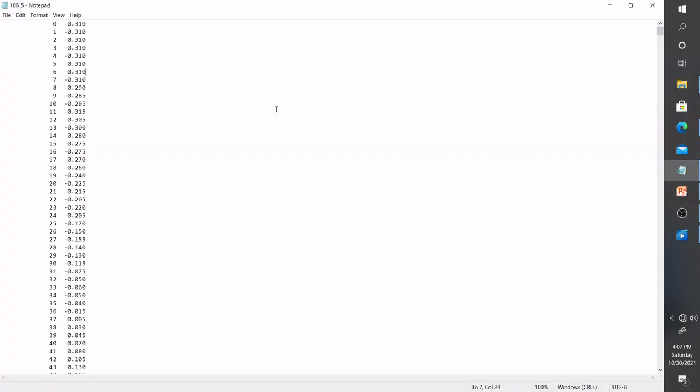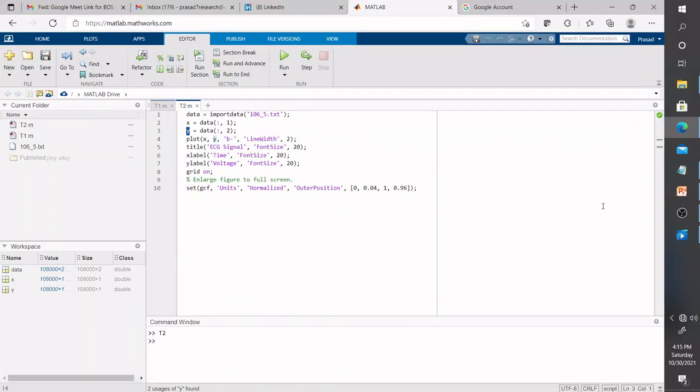According to the sampling frequency of 350 Hz, these are the samples we acquire at the output end of the sampling block. It has two columns. The first column is the number of samples, and the second column is the respective voltage values, and these discrete values will be the input for the digital filter. Let me discuss how the digital filter will respond to these discrete samples. First I will show you the ECG signal waveform with baseline wandering noise.